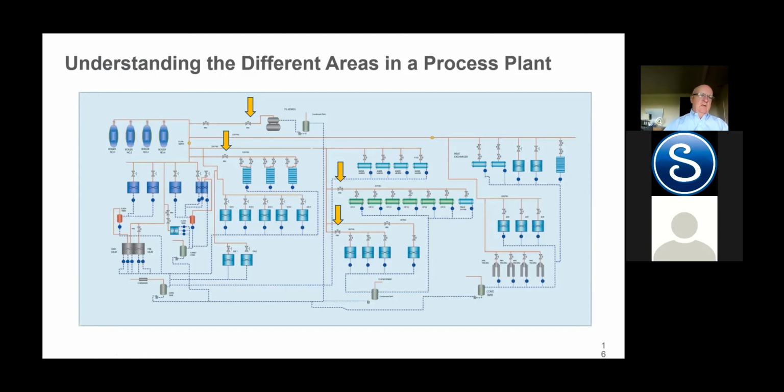Remember one thing, all sampling systems, we are not designing for operating pressure. We're always designing for maximum pressure and temperature. It's dictated by the safety valve that's protecting the system. It's not uncommon for plants to have multiple pressures. So understanding that we're looking at not operating pressure, but maximum design pressures and temperatures in the system.